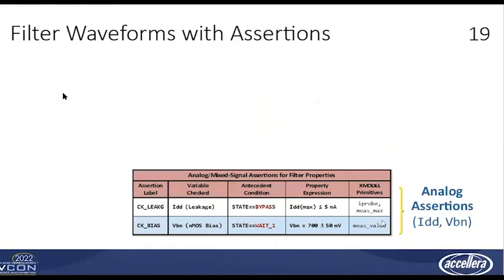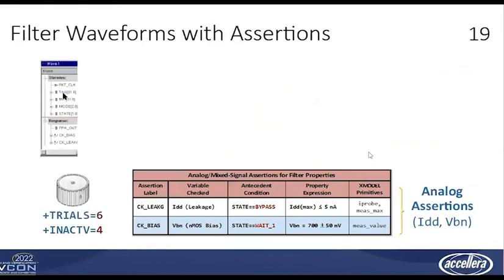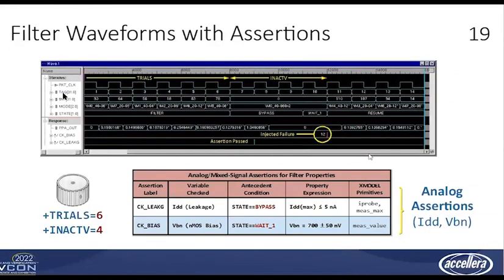So assertions are a valuable way to supplement UVM test sequences. Since they're highly localized to a circuit node or branch, for any violation, like this deliberately injected failure of the bias property shown here, you know exactly where to look for the underlying cause.